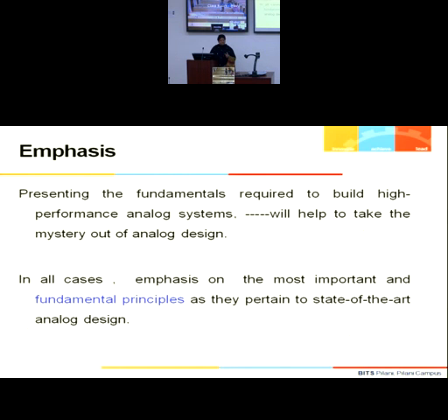Okay, so this is what we try to do, and there is a tool which helps us in this, which we call an analog HDL tool. We do the entire system in the analog HDL tool that is available in Cadence, and then we take up one block and design it in multiple ways. Every time I go on changing the block design and try to see the effect on the final output.